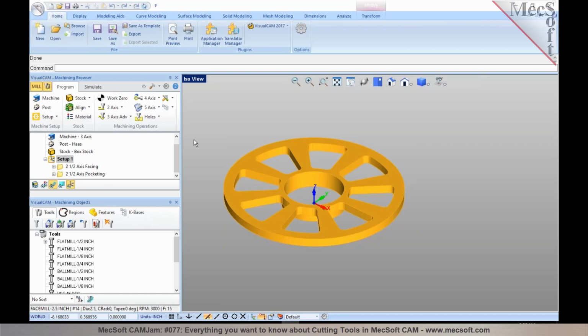So in order for you to optimize your feed rates for the machining time, these are the only two variables you're playing with. If you want to speed up your machining time, you have to reduce the number of motions and or increase the feed rate. That's as simple as that. So you've got to keep an eye on your non-cutting feed rates.